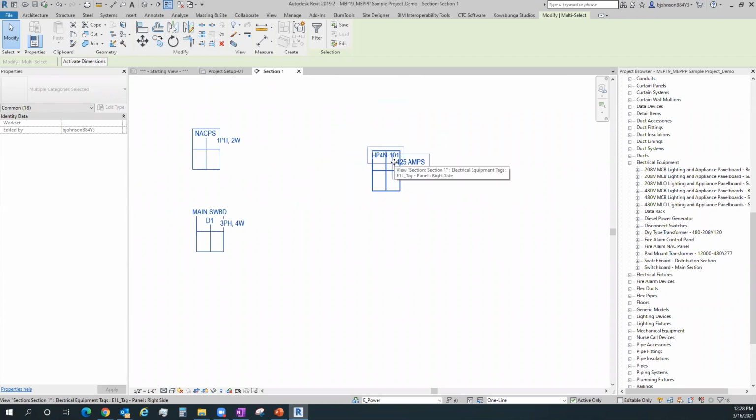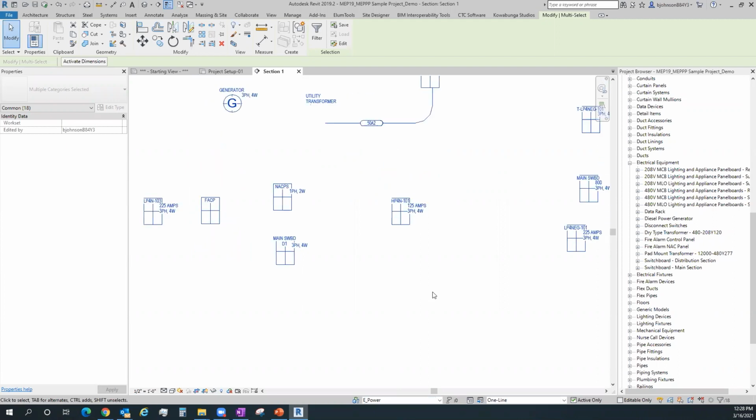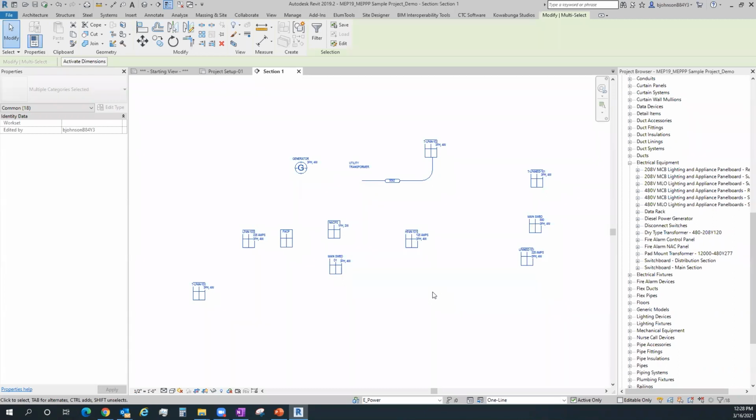So you could use the identity mark, type mark, mark number, whatever you wanted as one of your labels, and then a shape that you could draw from one line to another object, whether it's just regular line work or whether you use Conduit like we did. Totally up to you on how you want that represented. So yes, you could use this concept for any kind of flow type diagram inside of Revit using the real actual equipment. So the things that you would need for that would be the tags that you need for annotations.